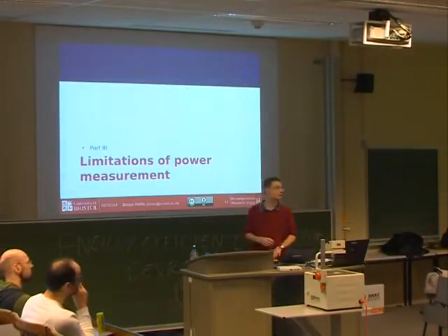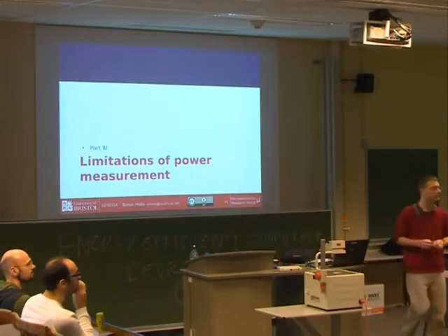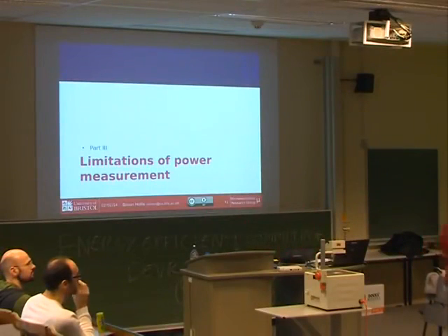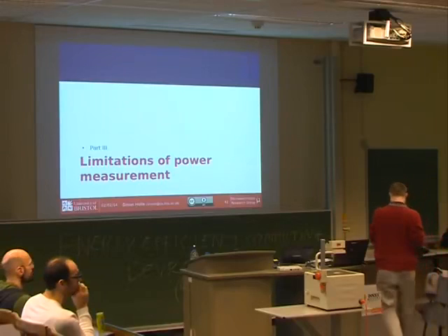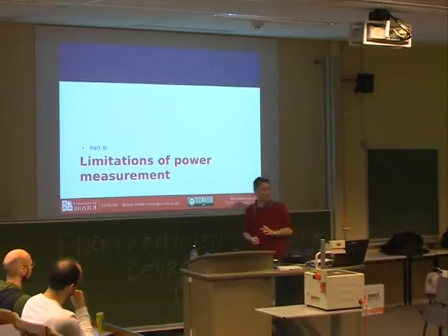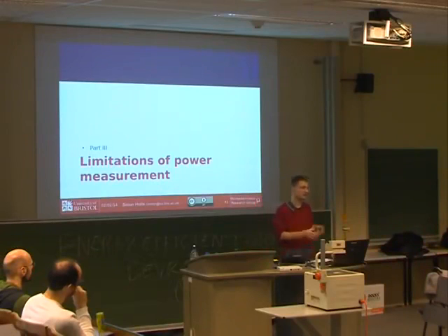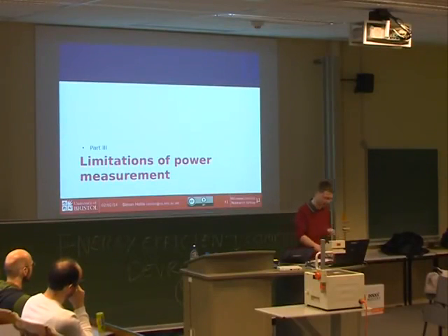Any more questions? Do we need to be concerned about the tolerances on the shunt resistor? Yes, absolutely. The power consumption measurement you get is directly proportional to the resistance. So if the resistance has a tolerance error, then your measurement is out by that as well. You can measure the resistance with a multimeter, and for this reason, shameless plug, in the open source design we specify a very tight tolerance resistor, 0.5%, to minimize any differences.